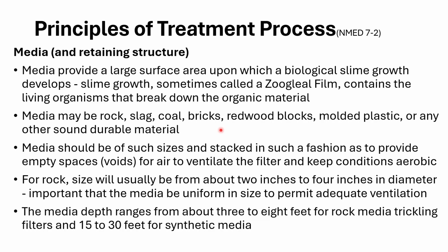Typically, though, for different flow rates, there's one I think that you really want to use, rock only, but take a look at that. Okay, so the idea is we want to be able to stack this filter media, whatever we're using, to make sure that we have enough voids or empty spaces for the air to ventilate the filter and keep an aerobic environment, an oxygen-rich environment.